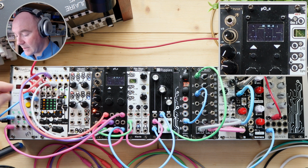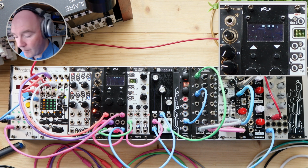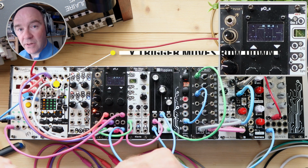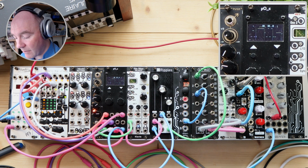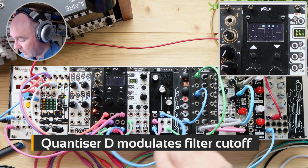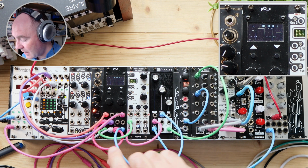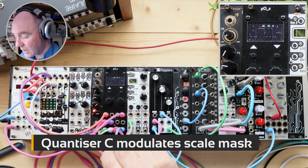So as currently set up, it's getting a trigger on the X input, so it's moving across each row. If it receives a trigger on the Y input, it'll move down to the next row in the sequence. So now what we have is a random source of triggers going into that Y input, and it will change the sequence being played. And as before, we have our two generators modulating the patch. So we have quantiser D modulating the filter frequency, and quantiser C modulating the scale rotation for the melody.